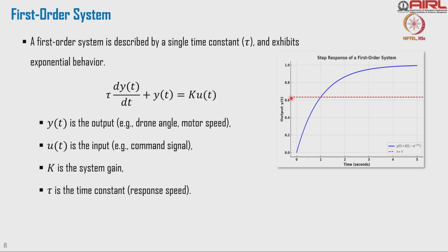And let us say at t equal to tau, this is the point, how it is crossing. We can analyze the first order system behavior. It is mostly used in motor speed control, or sometimes we even convert a command into a response for me to track. Having a discrete change is very difficult. Suddenly I can't go from 1000 to 1100. Even there we will use a first order system to convert the reference input to a feasible reference trajectory which can be followed by the drone.